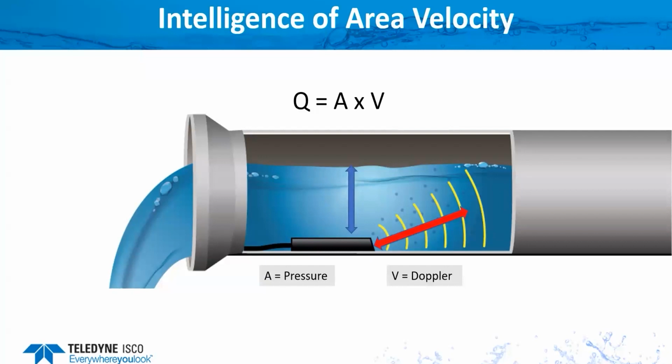Some advantages of this is that area velocity sensors can read forward and reverse flow. Even if the pipe surcharges 100%, the electronics are smart enough to use the 100% wetted area of the pipe. It will tell you how much depth it surcharged the pipe, and then still give you an accurate flow reading. And there's a bonus with the in-pipe area velocity sensors that it reads temperature also. So if you have rainfall infiltration, you see your levels and flow rates are going up, but the temperature is dropping. It's another indication that you have rainfall creating the I&I.